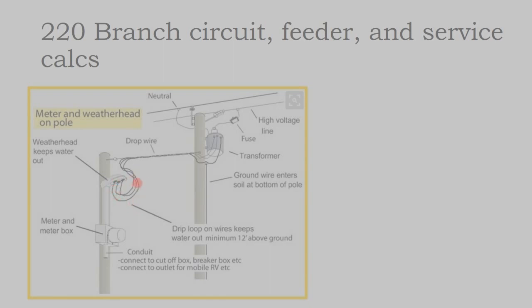Now, I've seen situations where the utility has come out during an install and installed the transformer and these power lines ahead of our commissioning, and they taped up the wires that were hot. And I've seen these wires sway in the wind and touch the side of a metal building and cause a ground fault that blew apart some connectors on my grounded solar array.